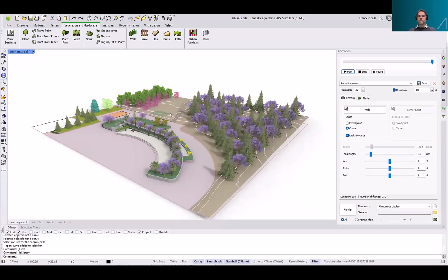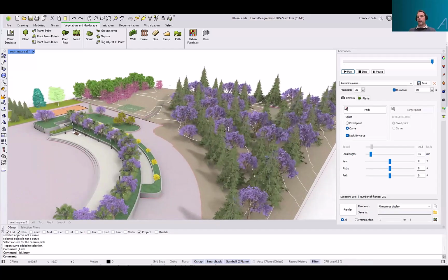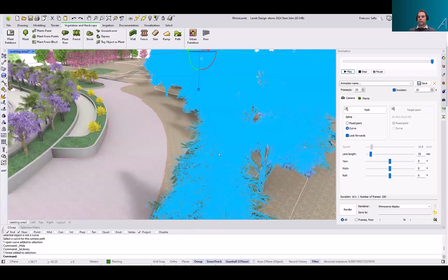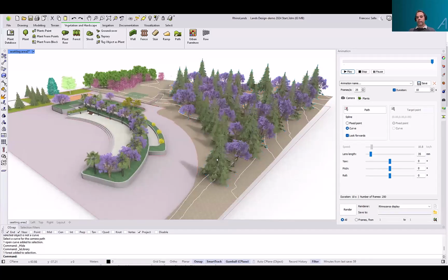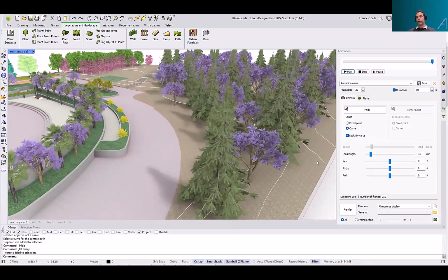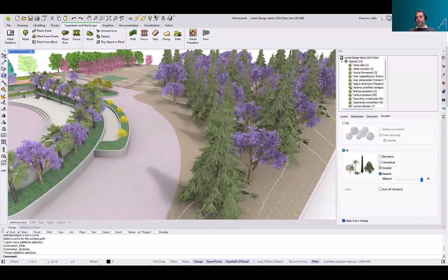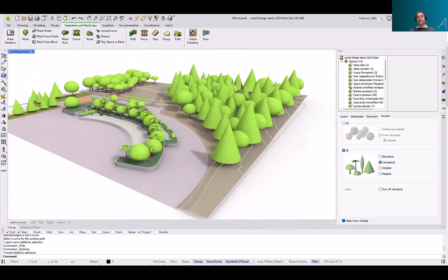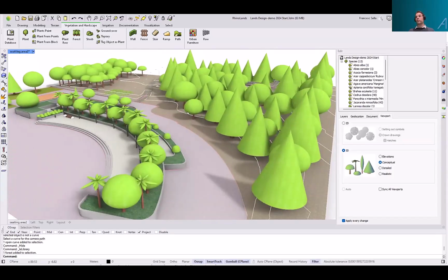Yeah, since Rhino is compatible with Enscape, there is a specific plugin to do a live synchronization of the models with Enscape. It works perfectly with all these elements that we have here. Just take into account that these plans will show up in Enscape according to the level of detail that we've got here. If we show, for example, the conceptual shapes, this is what will be transferred to Enscape instead.